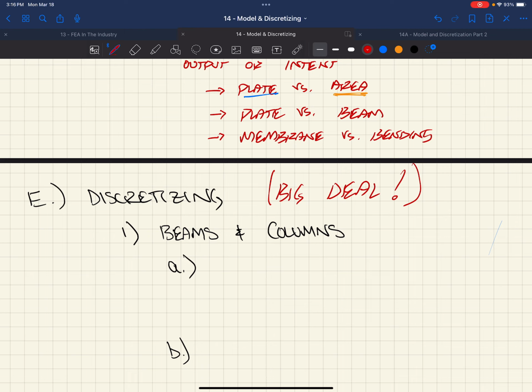Can you do that? I guess you probably can do that. But as we continue to actually model some projects here, I want you to run a convergence analysis when you're developing your model, right? And to do that, we need to adjust the discretization of our elements.